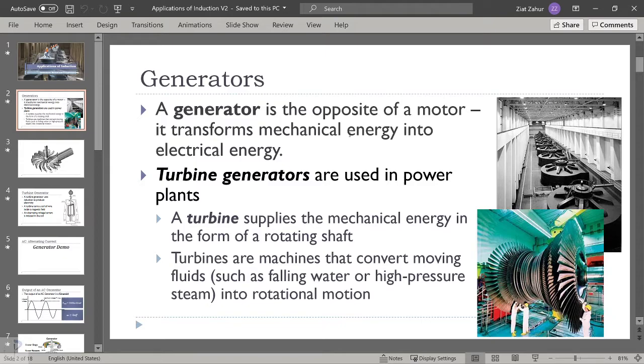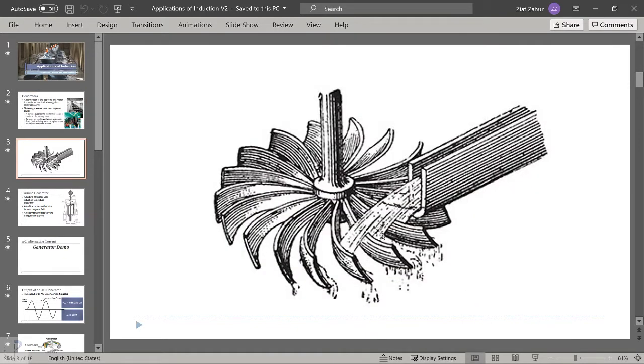You can produce electricity by spinning a magnet in a coil, or traditionally you can have the magnet in place and have the coil move around. Either way, you can generate electricity. First of all, you do need mechanical work to spin. You can get the mechanical work if you think about water wheels. When the water falls onto this wheel, the water pushes onto the wheel and it spins and rotates. We are converting gravitational potential energy, mgh, of the water crashing into the wheel into rotational kinetic energy for the wheel, right?